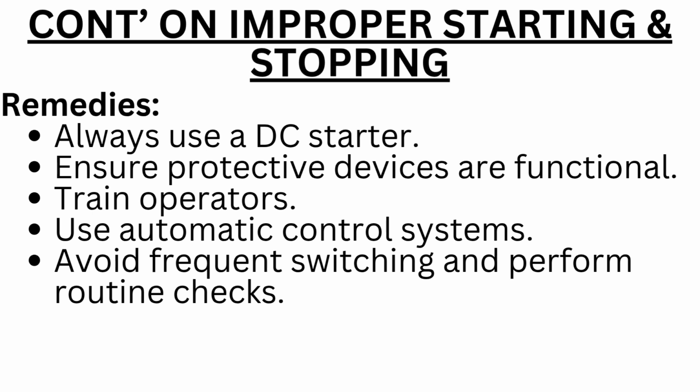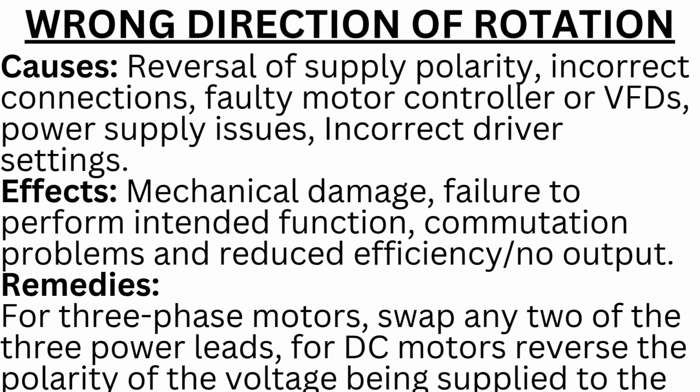Ensure protective devices are functional. Train operators. Use automatic control systems. Avoid frequent switching and perform routine checks. The next operational failure is wrong direction of rotation.